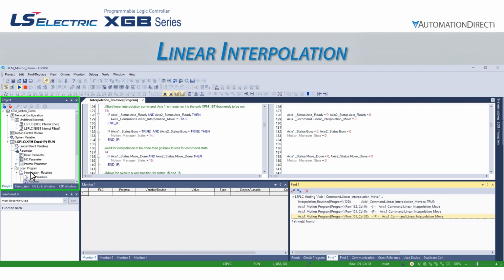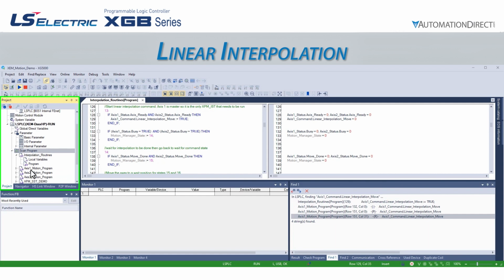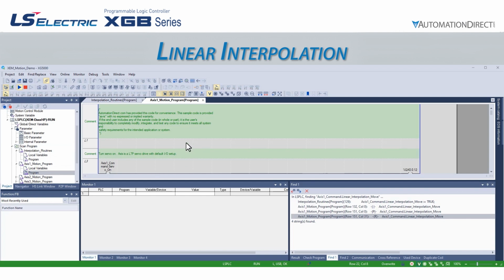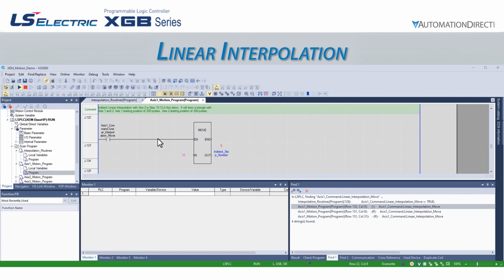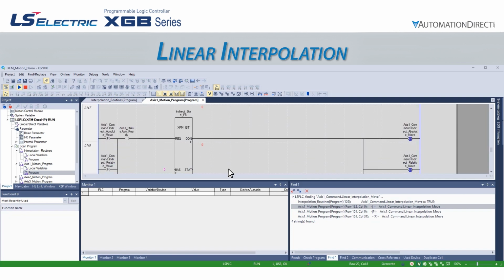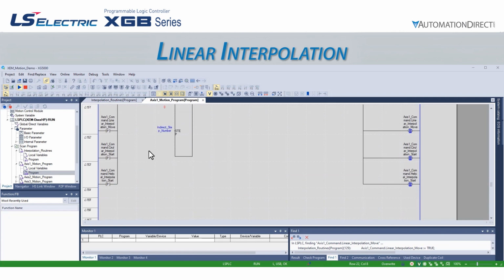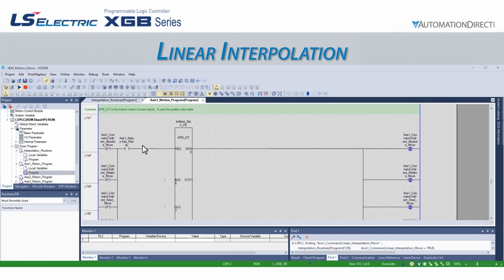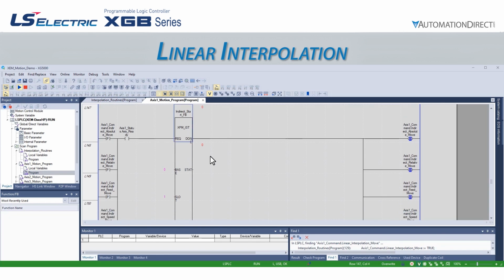We go to the project window on the left side of the screen, maximize the Axis 1 motion program heading, and double-click on program. The first entry is on line 132. And we see that if this bit goes high, the PLC will copy a 10 into the variable indirect step number. If we now look at line 151, we see that a positive transition or rising edge one-shot instruction will activate the indirect start function block.